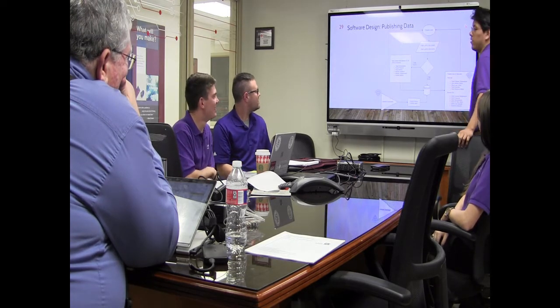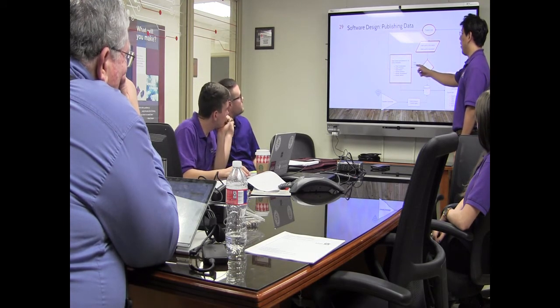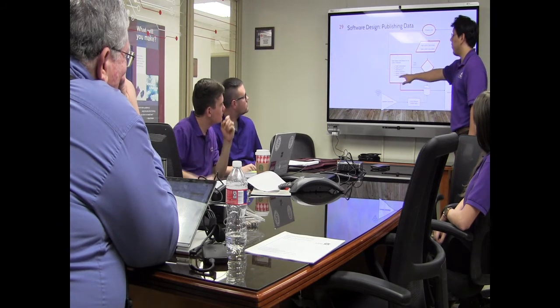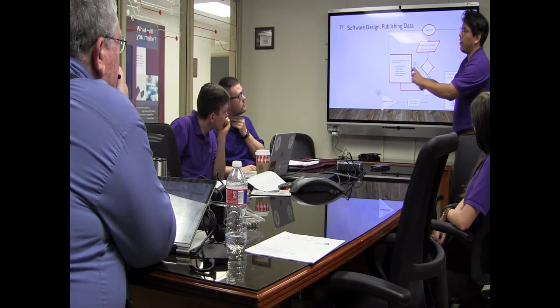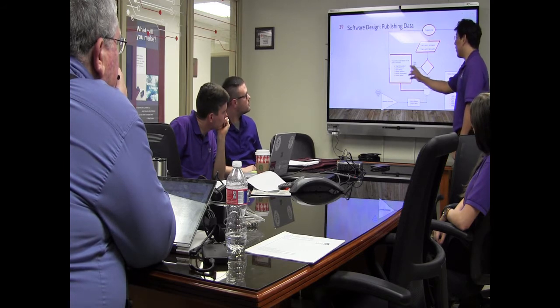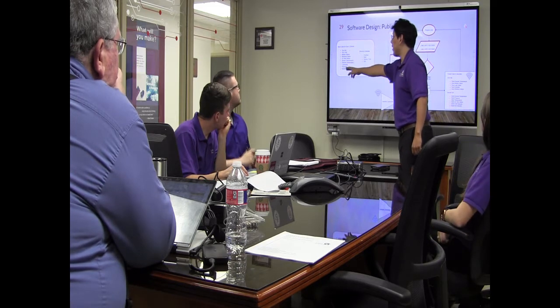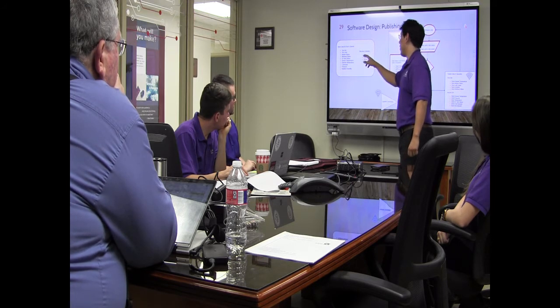Okay, so now this is publishing to Cayenne. If you just click once, we're going to go through checking the reading temperature, reading pressure, reading motion, monitoring moisture, monitoring temperature, and monitoring motion, and that's just reading the sensor data from the PIR and the moisture water level. What that does is it reads it every 2 seconds and puts it in our little storage. If you click it once more, the way it works is we have all the indicators that are on the dashboard listed, and each of them has its own structure. It's a structured variable, and it holds its channel, its data, a sensor type, and its unit.